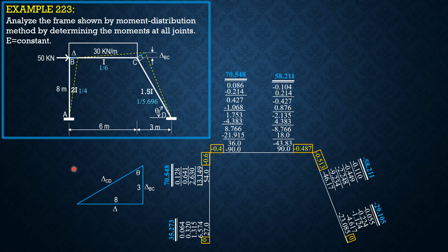So moment AB side sway is negative 6 EI, so EI is taken 2, then delta over length 8 square, so negative 3 delta over 16. For BC, the rotation is counterclockwise, so it is treated negative. So it is negative 6, EI is 1, then delta is negative 3/8 of delta over length square 6 square.